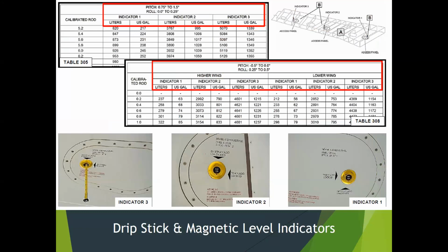If I have, say, 4 sticks in here, you can see if I were to use that most outboard stick, I wouldn't get any kind of level indication. They would typically call these number 1, 2, 3, and 4, 4 being close to the wingtip, 1 being close to the root. So I would use stick number 3 in this case. I would drop it down until the top is even with the fuel. It's got a little float on the bottom. And now my stick would be hanging down, and there'd be a certain number of inches that we would be able to read it hanging down.